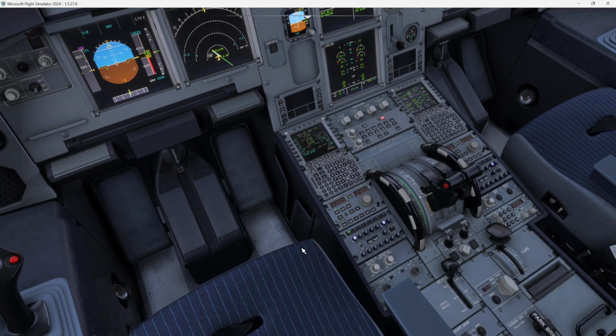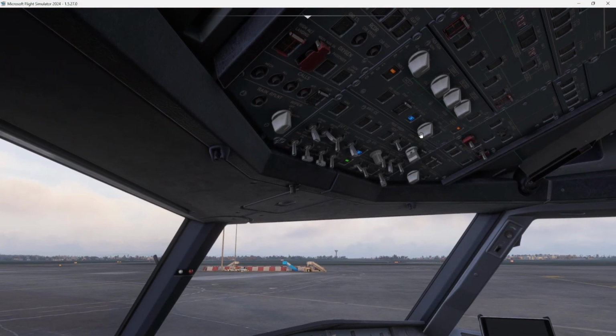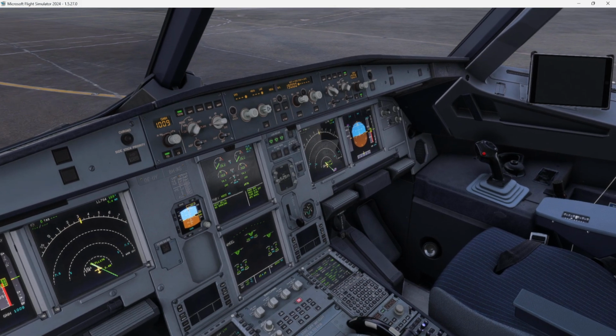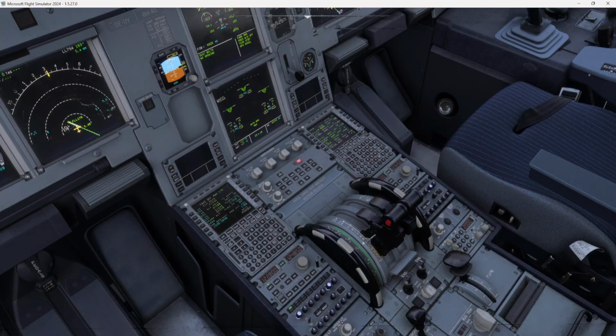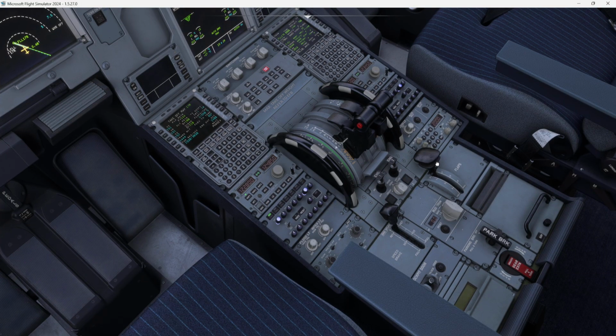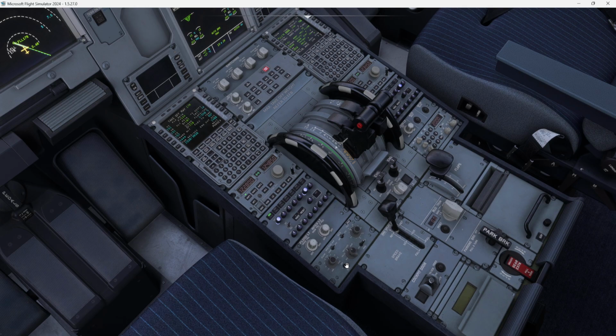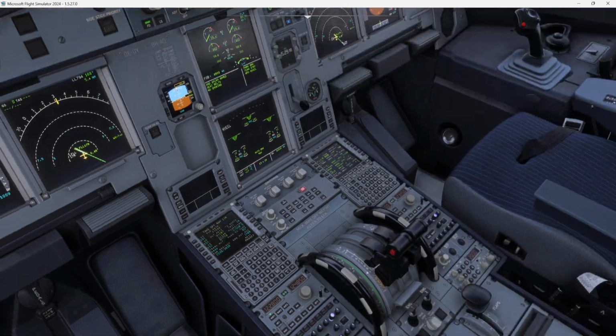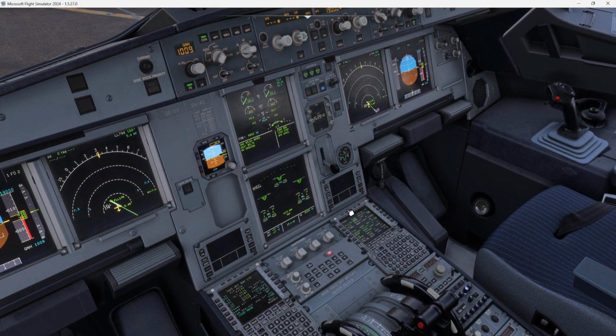But well, let's go. Engine 1 available. Engine mode selector normal, APU bleed off, APU off. Let's get taxi lights on and max here, autobrake, speed, flaps 1, radar, trim neutral, and speed brake armed. Radar and windshear predictive is on and auto.